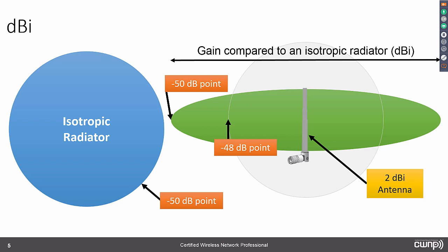And this is going to be dictated by the kind of antenna. If I have a parabolic dish, for example, then I'm going to see most of the energy going out in one direction from that antenna. And behind the antenna, above and below the antenna, I'm going to have very low output power, is what it's going to appear to be. Now again, remember, I don't have any more RF output power than what I'm putting into the antenna.